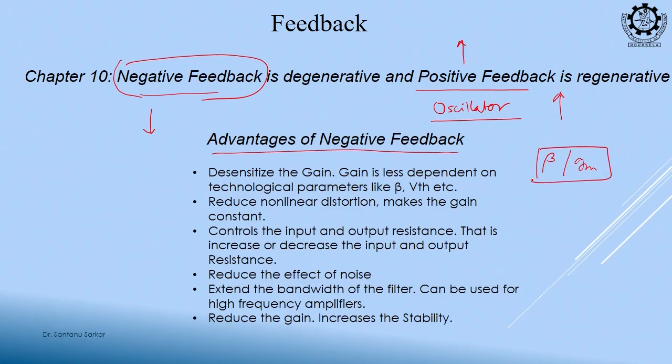As a designer you have no control, so your open loop gain you have no control over. Now, in negative feedback, your gain is dependent on some resistance ratio, that is the feedback factor. The feedback factor you can choose.